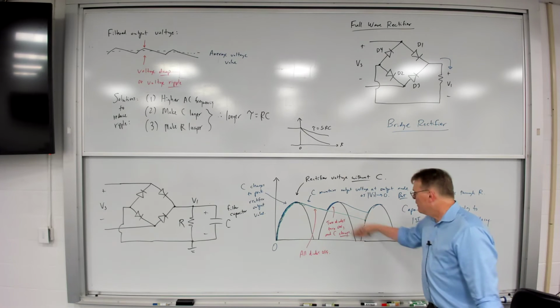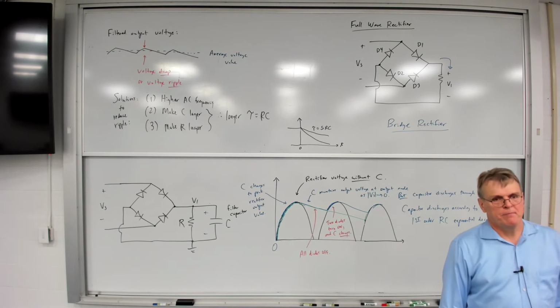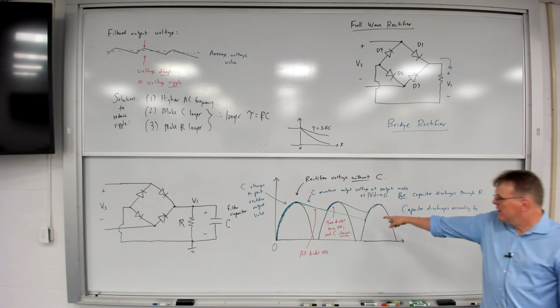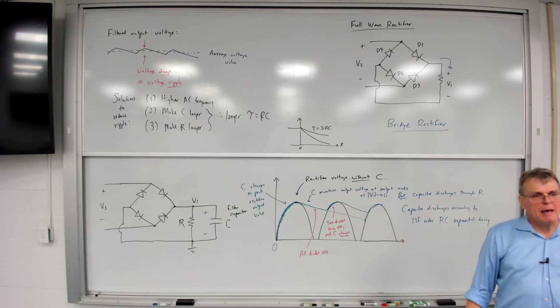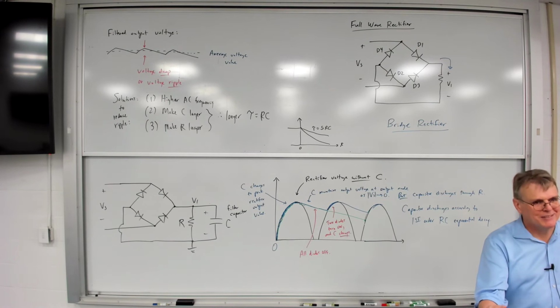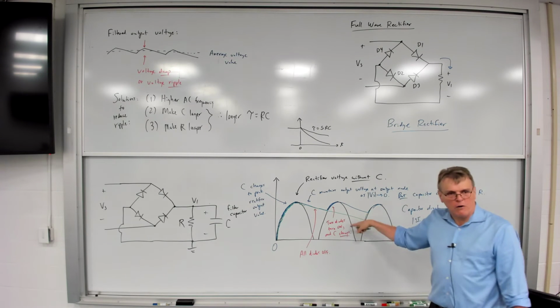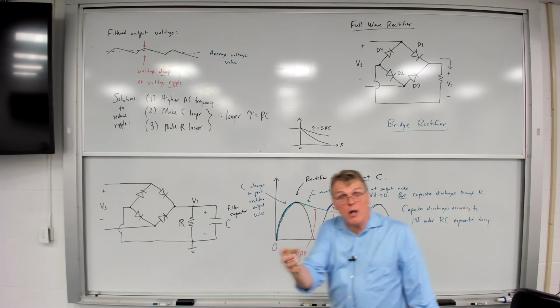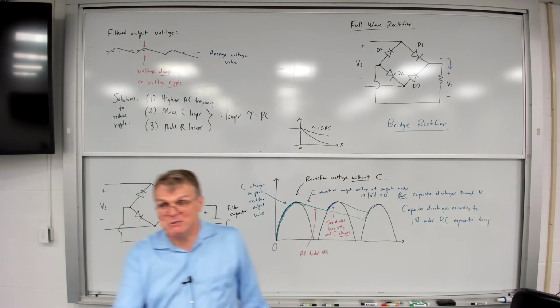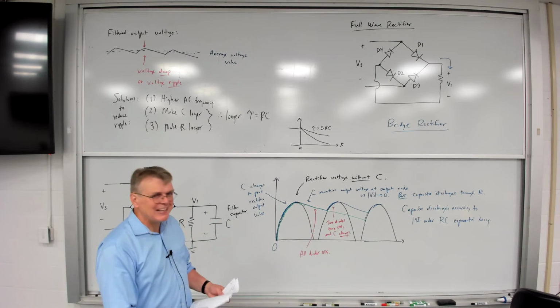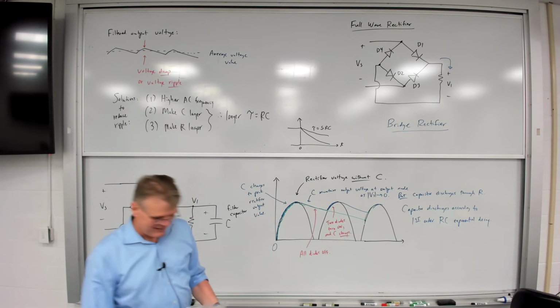So the capacitor only gets recharged half as often. So if I have a half-wave rectifier, what is the drawback I'm going to have? More ripple, okay? Because it's going to take longer before I get this thing to recharge. Once again, effectively you're lowering the frequency. That's what's happening here, because now you're only getting every other waveform.